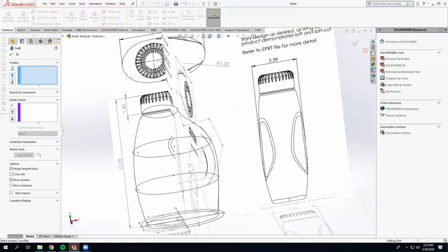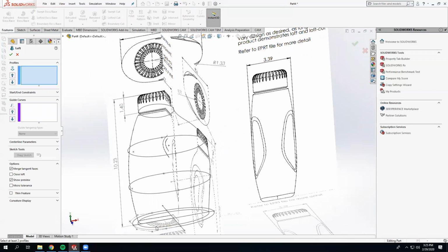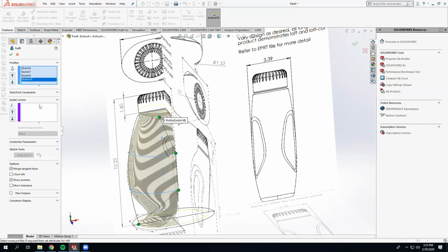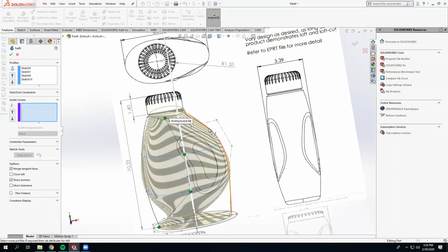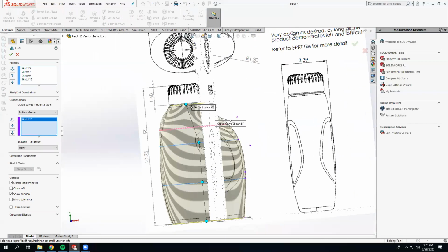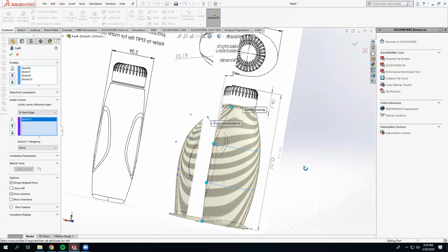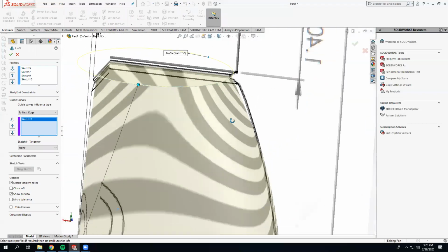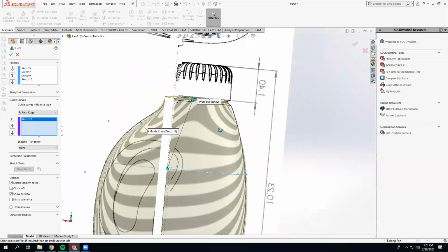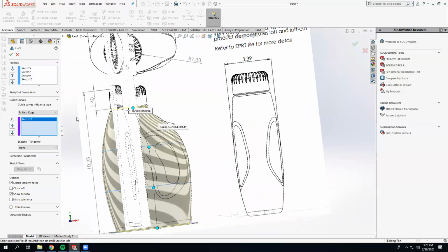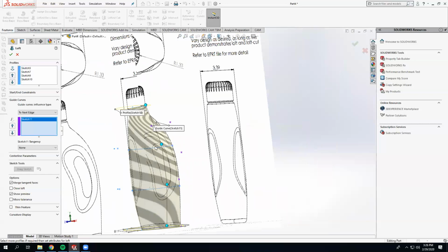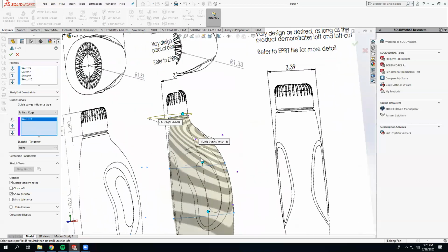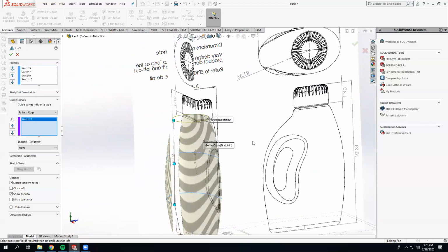So I could run the Loft feature right now and see what's gonna happen. But then I get that little thing right there. Maybe this is something that I could use this edge with, right? So I can skip the step of creating another guide curve, so it might be easier for you. So I did next to edge. So it's basically pulling this edge into my guide curve. And that looks fine.